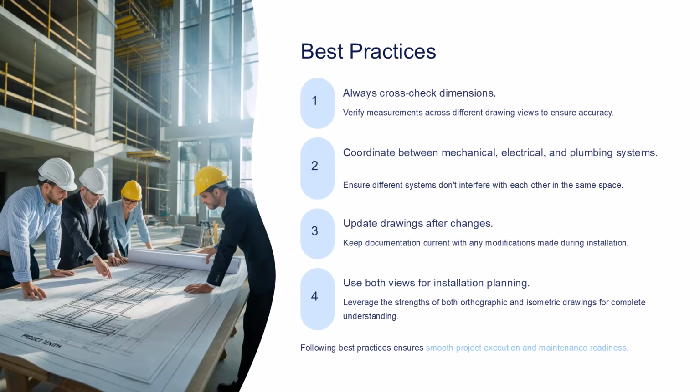Best practices. Best practices in working with drawings include always cross-checking dimensions and coordinating across all services. Updates should be made immediately after changes. Both orthographic and isometric views should be used together for complete understanding.